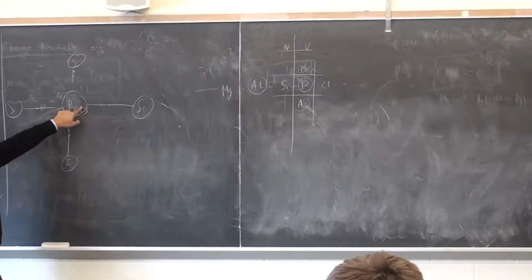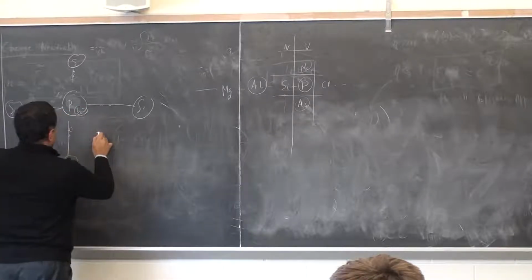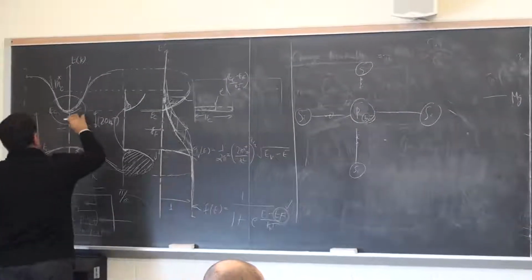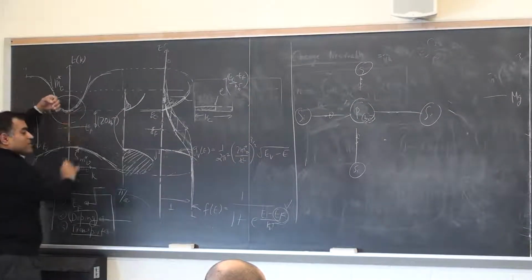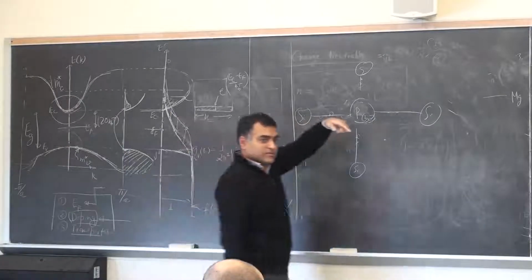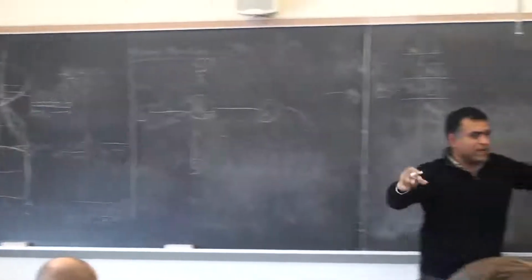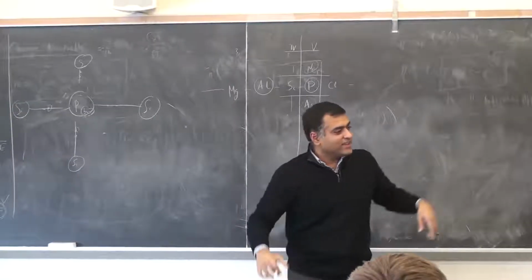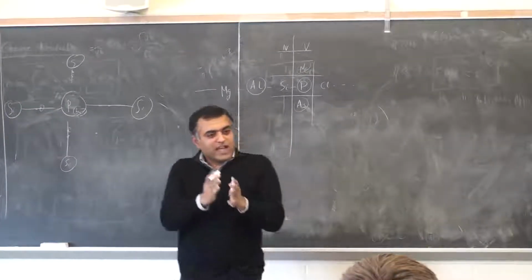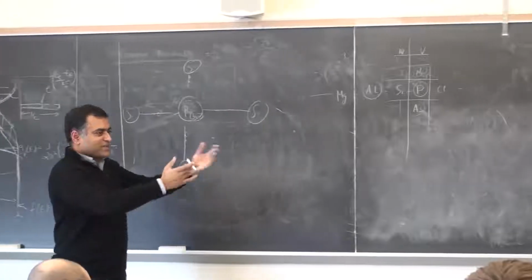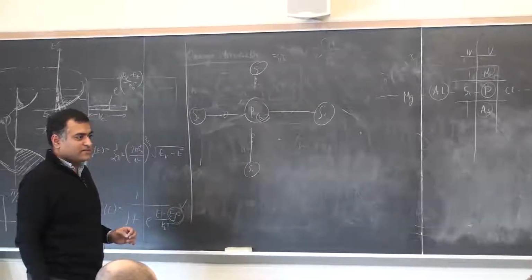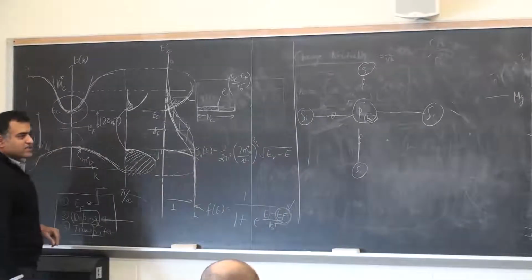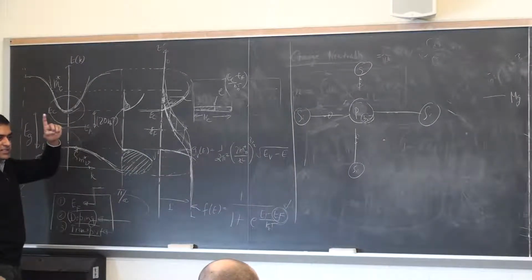So that electron that's left over has an energy level, and I'm going to show that later. Remember, this is an extra electron now. If I had the whole silicon wafer and I plucked out 1 silicon atom and put in a phosphorus atom there, then that crystal has one extra electron compared to the crystal which had no phosphorus atom. It's very important to note that. Therefore, this cannot be the whole band structure. There must be one extra energy level somewhere.